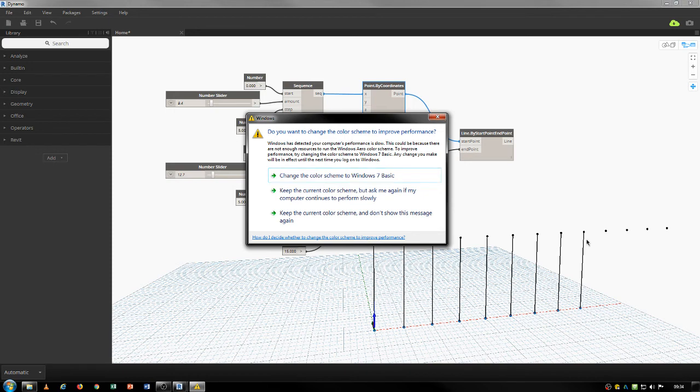So that's the longest. You also have something that starts with cross. It could be cross-referenced or something like that. And then what it does is that any single point from each of the list is connected to any single point from the other one. So what's going to happen is this, that, this, that. So now every single item from each of the list is connected to every single item from the other one. A lot of times when you are doing scripting, that's causing issues for you because you have 2 lists, you want them to do something for you and it's not doing it correctly. It's because the way you're defining the connection is not right.